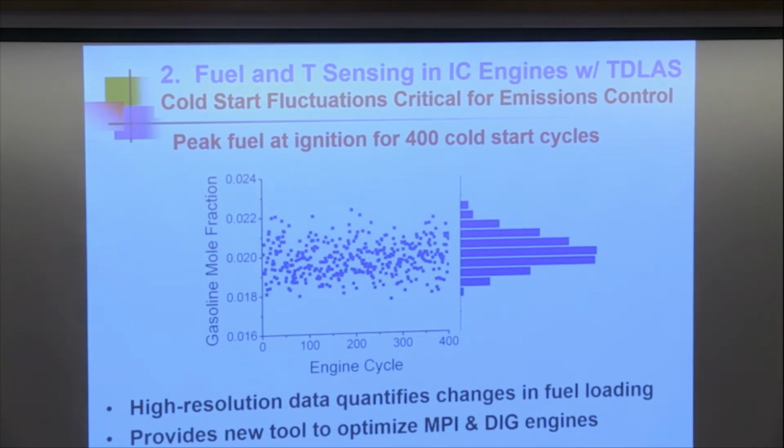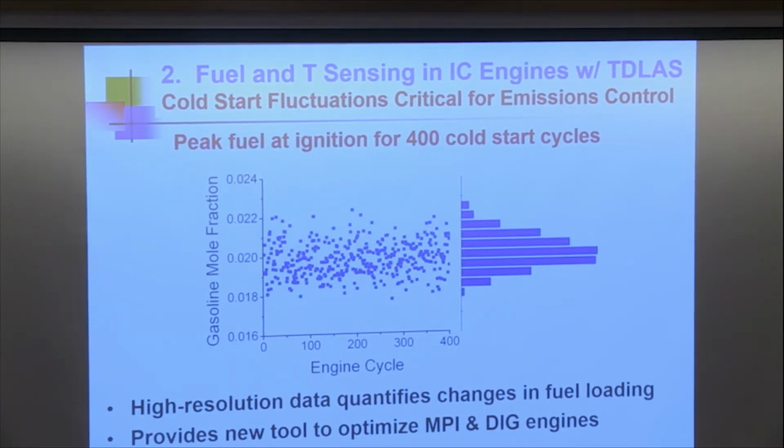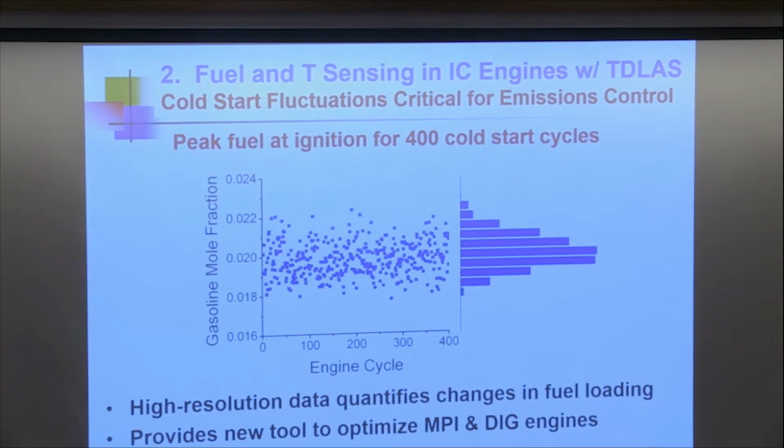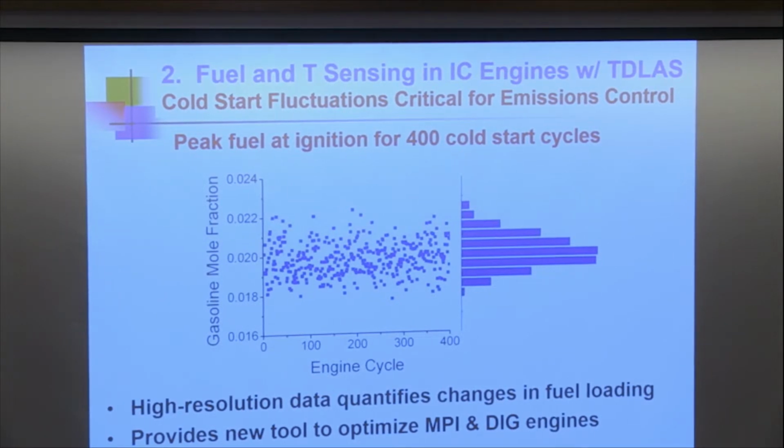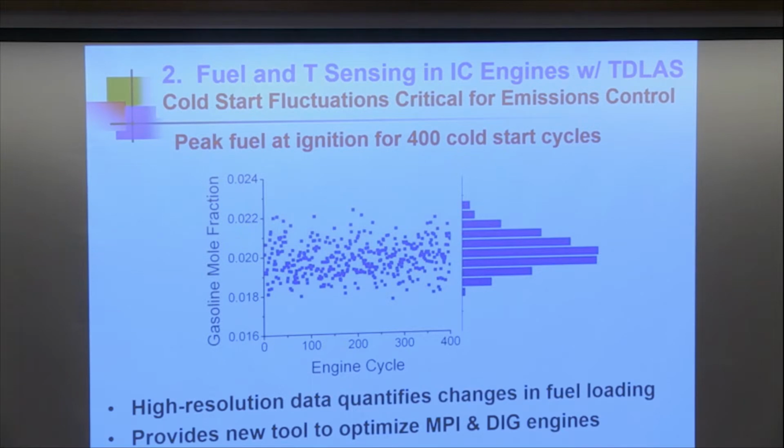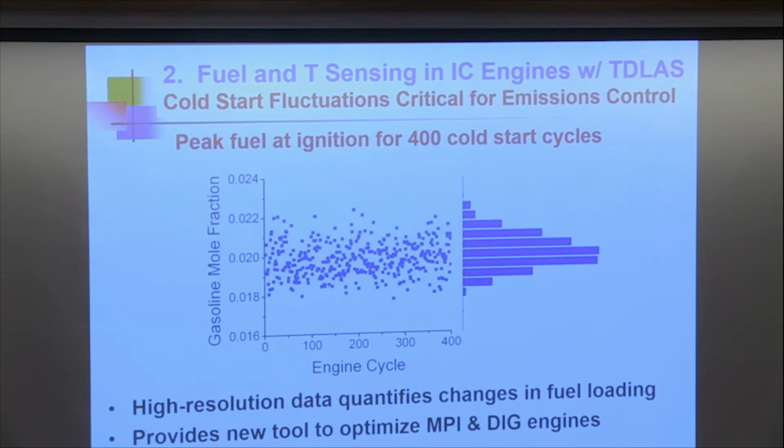So they're worried about what's going into the engine every cycle and what's coming out as they do their CFD. Among other things, we found that in these racing engines, there's kind of a boost intake. And the pressurized region oscillates in pressure. So we found oscillations in the droplet loading, which then the droplets have to evaporate. So what's going into the engine is changing with time in a way that they didn't actually appreciate. So that was good. That company is very happy with what we're able to show.